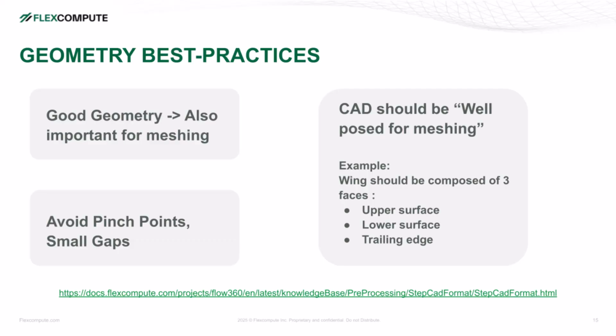This includes avoiding pinch points and small gaps between surfaces. Your model should be well posed for meshing and be composed of solid bodies, not sheet bodies.